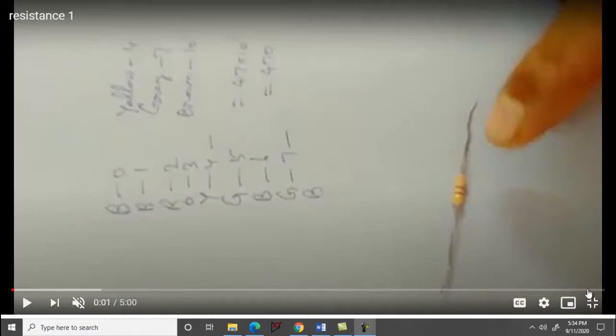Either logical 1 is appearing at the output or logical 0 is appearing at the output. How do we know? It is in the voltage level. How do we represent logic 0 and logic 1 in terms of voltages? For this IC, namely your 7408, plus VCC and minus VCC, we will be giving plus or minus 5 volt from the regulated power supply. So usually logical 1 will be plus 5 volt and logic 0 will be minus 5 volts.